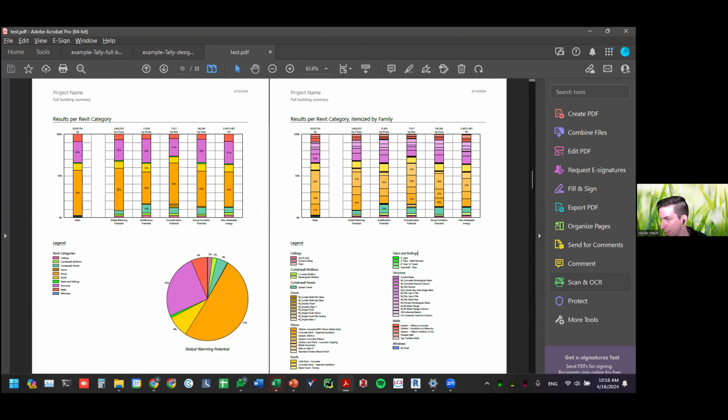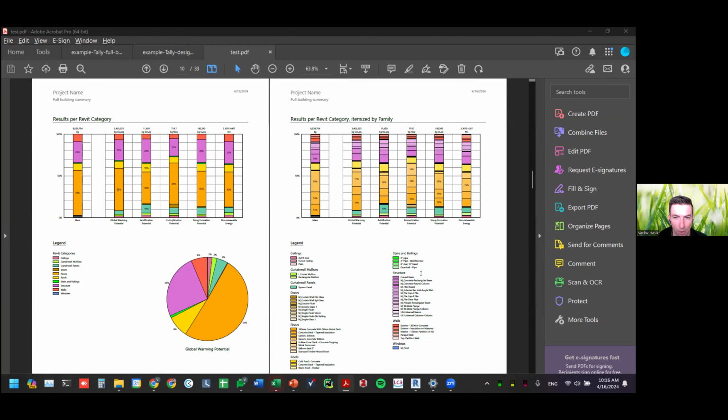There's another quick question. What is the best method to take off the steel amount, by steel profile or volume? Because there was a notable difference between these two methods in my project. Great question. It comes down to how your team actually models the steel profiles. If you are confident that you are actually modeling the profiles to their true dimensions, then doing the takeoffs by volume makes complete sense.